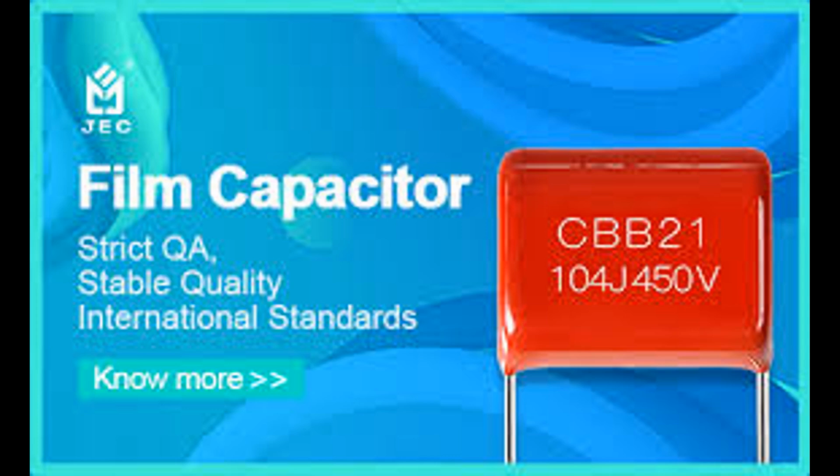5. Sensitivity to overvoltage. Dielectric breakdown. Although film capacitors have a high dielectric strength, they can still suffer from dielectric breakdown if subjected to voltages significantly higher than their rated capacity. Overvoltage can lead to internal damage, even in self-healing capacitors, and cause capacitor failure. Unlike electrolytic capacitors, which are more forgiving to momentary overvoltages, film capacitors can fail abruptly when subjected to excess voltage.